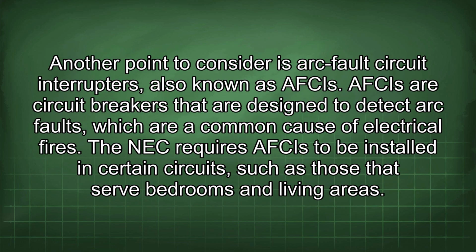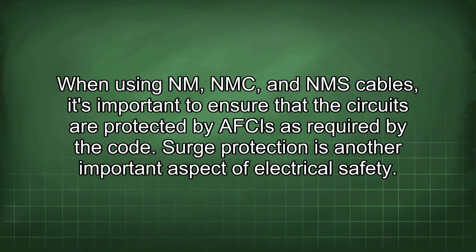Another point to consider is arc fault circuit interrupters, also known as AFCIs. AFCIs are circuit breakers that are designed to detect arc faults, which are a common cause of electrical fires. The NEC requires AFCIs to be installed in certain circuits, such as those that serve bedrooms and living areas. When using NM, NMC, and NMS cables, it's important to ensure that the circuits are protected by AFCIs as required by the code.